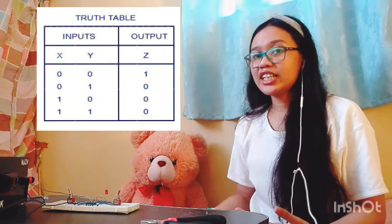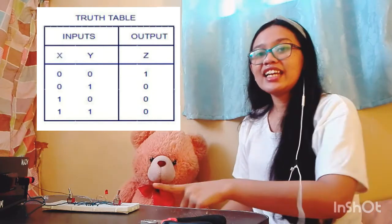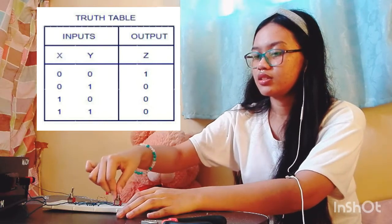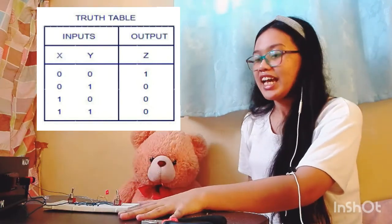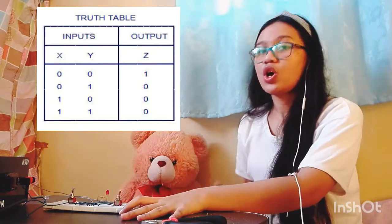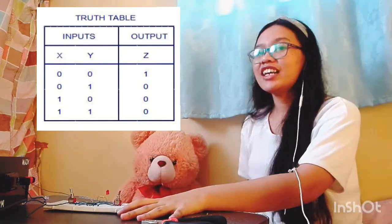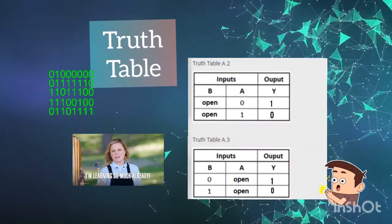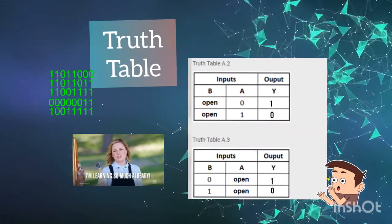Now, let's test our first circuit. Let's turn the power supply on for the 5 volts VCC. Here we have our circuit. Since NOR gate is the opposite of OR gate, the LED will only turn on if both of the switches are in low input. And the LED will turn off if any of the switch or both of the switches are in high input. Here are the other truth tables with open input.